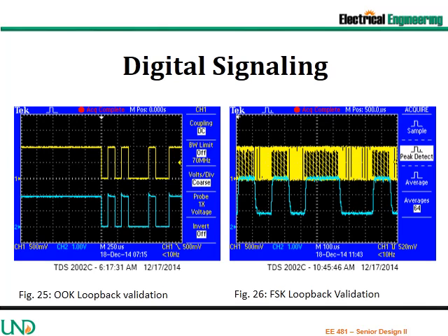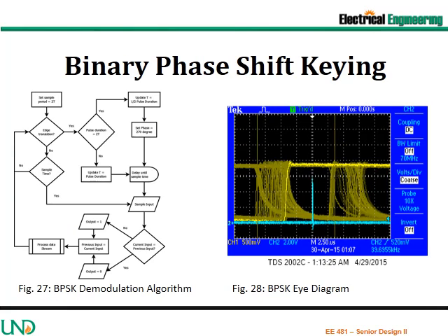The phase frequency detector has a minimum and maximum voltage that it will output. This minimum voltage is right on the threshold of the low voltage of the RS-232 receiver. The data rate for the binary phase shift keying was 33 kilobits per second, with one synchronizer bit included for every 5 data bits. At 5 data bits per sample, this results in a sampling frequency of 6.67 kHz.